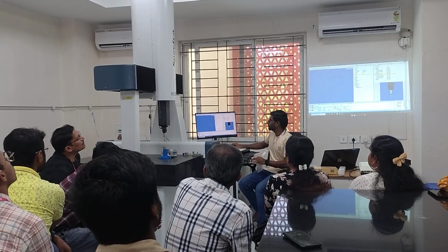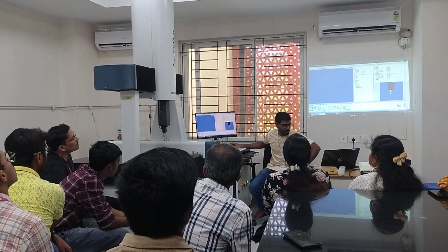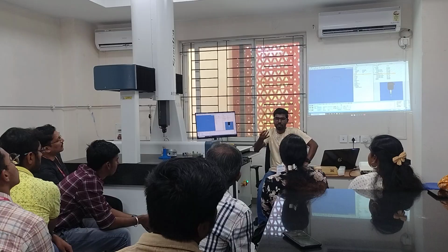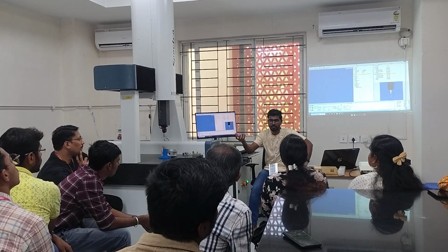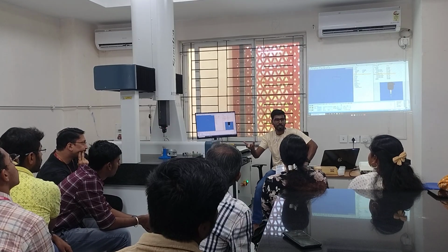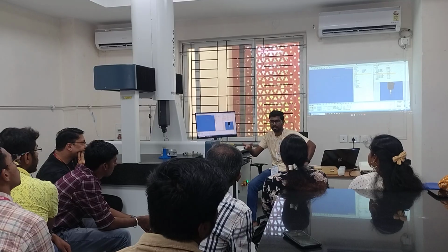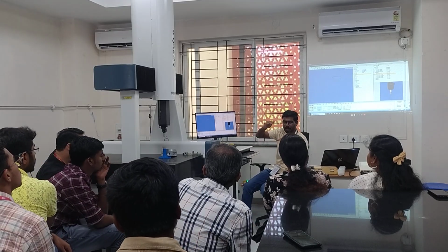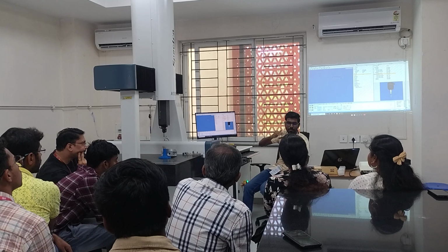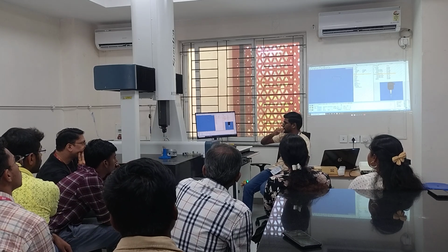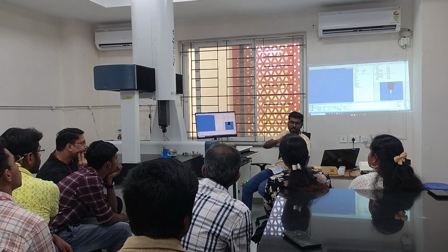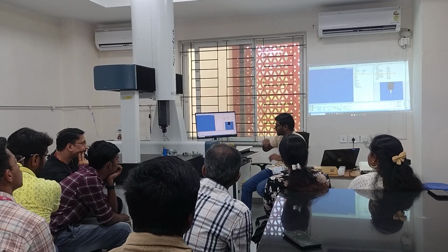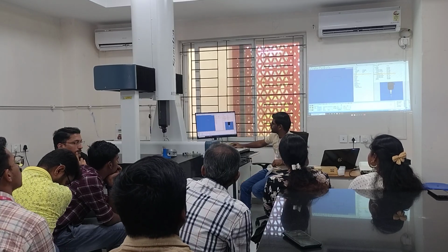Tolerance. Okay. So I forgot to tell about tolerance. So what is GD&T? Geometric dimensioning and tolerancing. So if something goes out of tolerance, there must be some repercussions. There will be some repercussions, isn't it? Just like the child was getting beating. Similarly here, upper limit and the lower limit. The difference between them will be called a tolerance. Okay, you might have seen in the drawings plus and minus something. So that is nothing but tolerance.